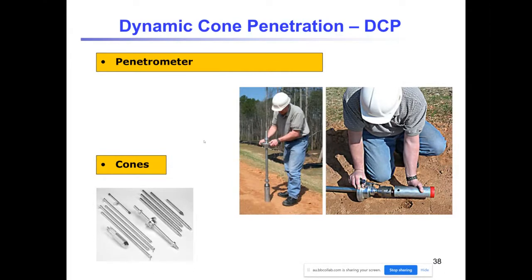All right, so let's talk about the next testing method that we are going to use in this project. The next test is the dynamic cone penetrometer test. Here you can see the equipment. Again, very simple equipment. So again, very cheap, can be done with only one person, and you can get lots of results within a couple of hours. So you need to keep this shaft upright.